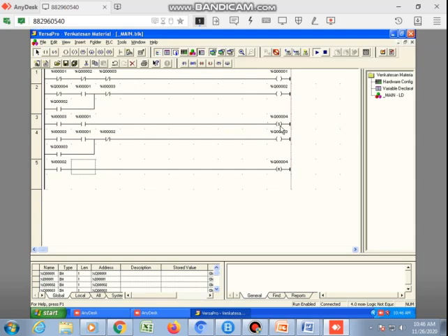Immediately I will enable my electromagnetic switch, that is set Q4. The same condition will start my robo arm to move in reverse direction. How long will it move? It will move until it reaches position I2. When it reaches I2, I should stop my robo arm. Also, I should reset my electromagnetic switch, which will drop the material in the reservoir tank.